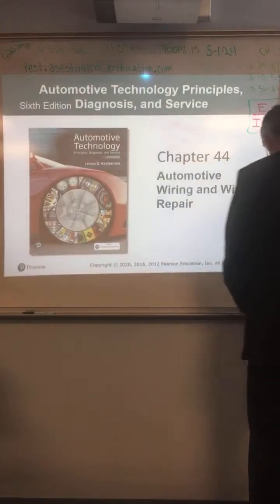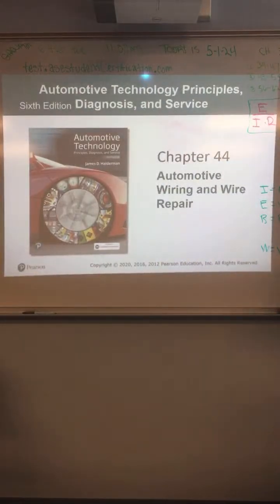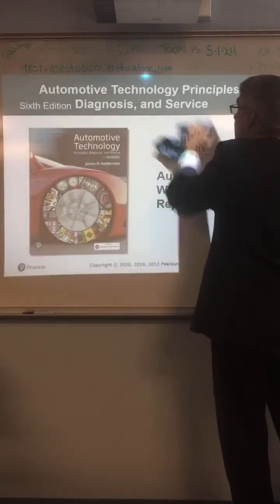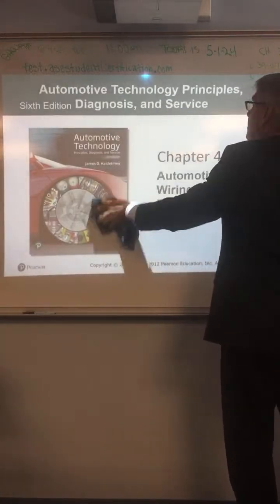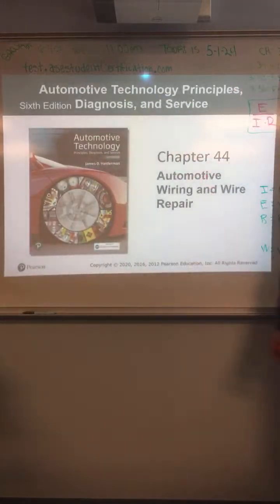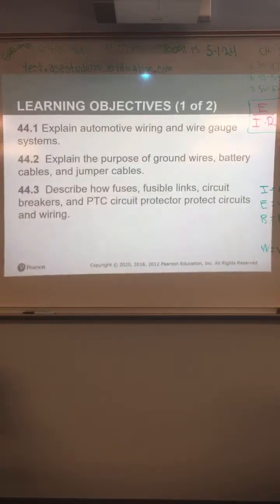They're also measured in square millimeters because somebody decided we had to adopt the metric system years ago. A lot of times on a schematic, you'll see the wires shown in square millimeters as far as diameter goes. Okay, we're gonna go through that wire gauge system. There is obviously a chart for that in the book.